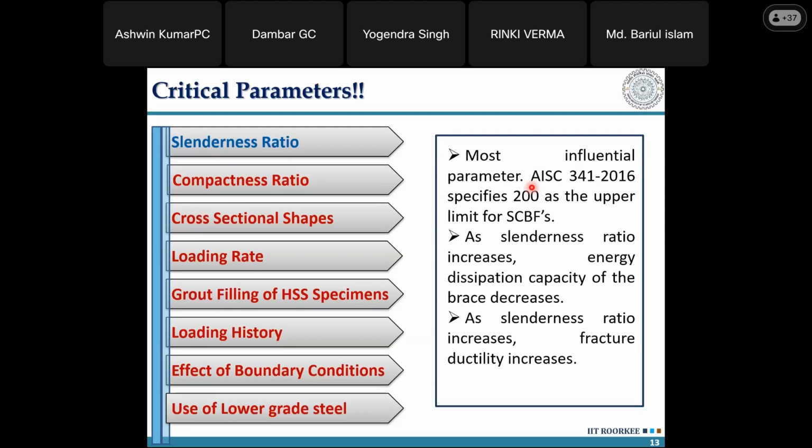Yes, Dr. Narayan, IS 800 section limits it as 120. But if you look at section 12 itself of IS 800 2007, you will find the slenderness ratio 165 there. And then in IS 1893 also, there is a limit that is given there, right? So let's understand why it is given as such. You understood, right?